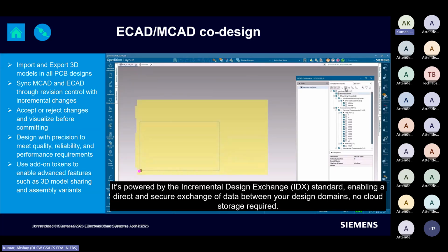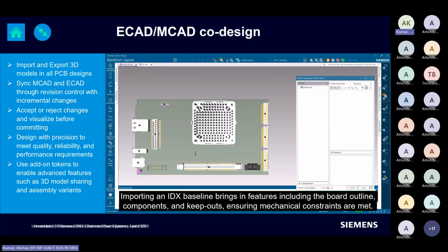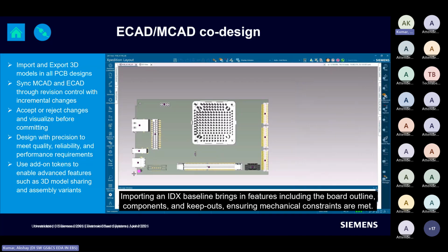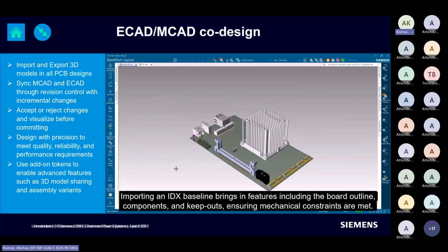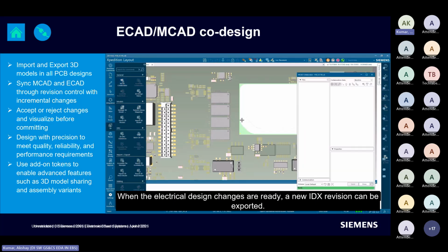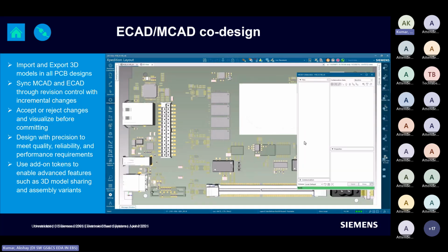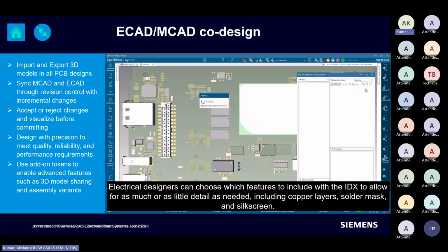Now, the advantage that you will get here is that any change that you are trying to update in your board, you can actually highlight before you apply it, right? With just a single click, you can see the input that is being shared by your mechanical team getting updated here. Okay. And once it is updated, your task is done. Now, what you can do is send any additional files that you would like to give to your mechanical team, right? You can have a selected component or the entire board. That's totally your choice. Okay, you can enable or disable that.